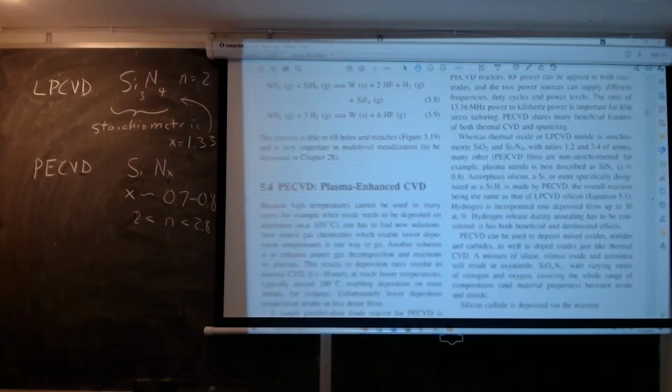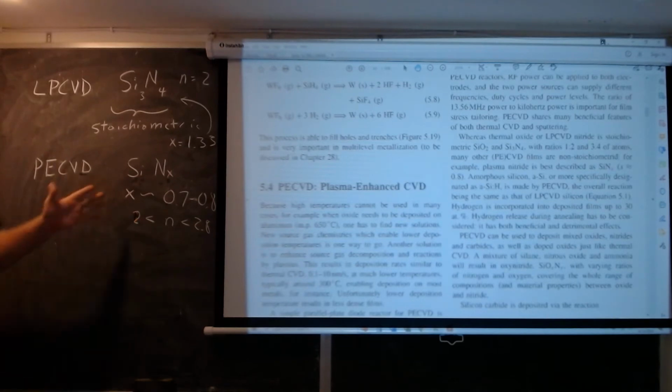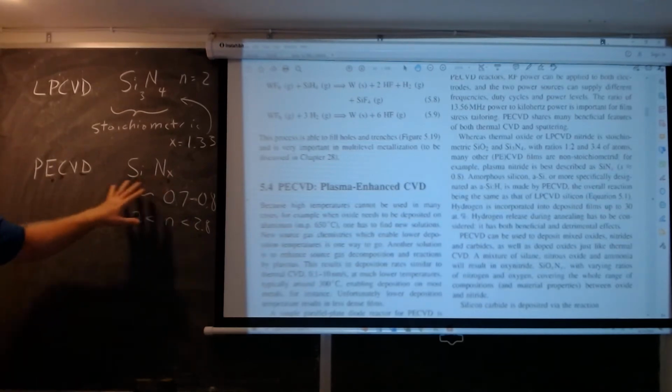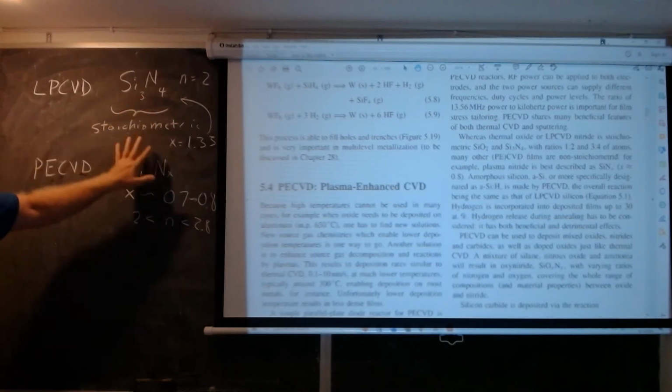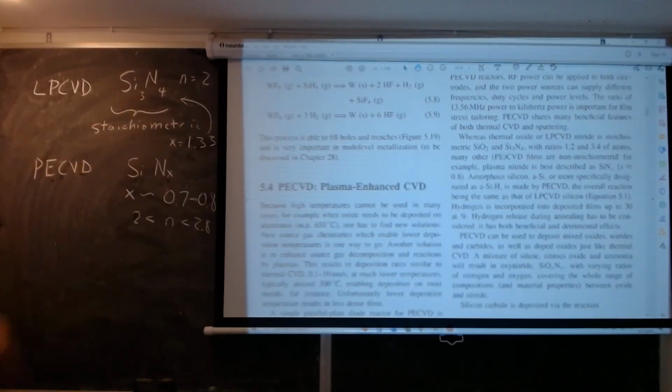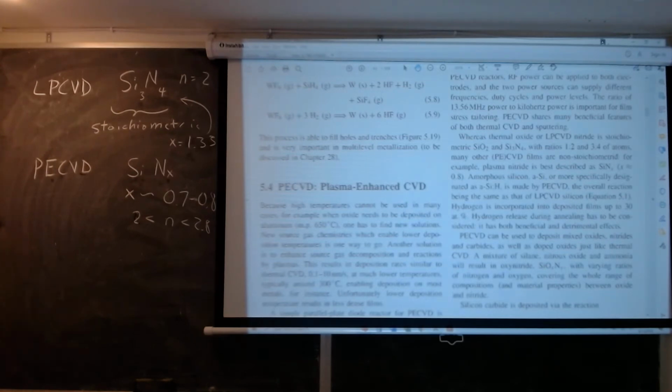Now, you do pay. One aspect of silicon nitride by PECVD is that you can vary the composition, whereas for LPCVD it tends to be purely stoichiometric, meaning this ratio of silicon to nitrogen atoms is fixed.